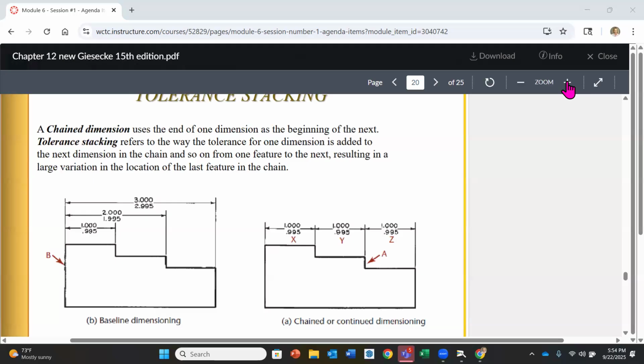And I'm telling you that when cost reductions need to be created, especially in the manufacturing process, the first thing they're going to do is pull out the drawings. They're going to look at every one of the tolerances and they're going to say, is this one necessary? Is this one necessary? Is this one necessary? And you want to open up as much as possible. You as the designer need to take that into consideration up front. You want to make sure that you're maximizing the tolerances. You're not putting stuff on that isn't necessary.